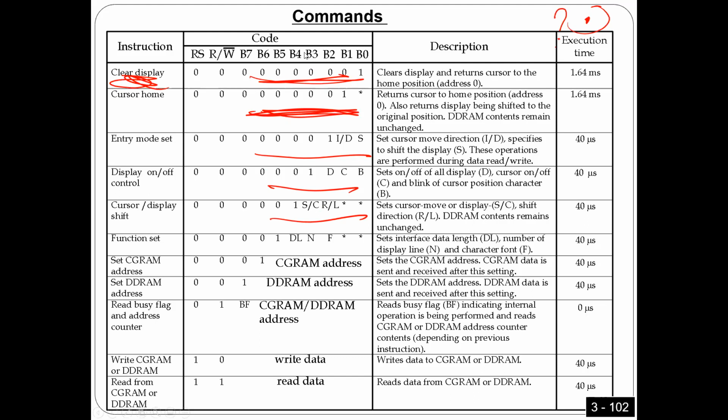They made it so that when you send this number, the hardware will do the display or whatever. So almost everything is the same, but maybe these numbers will change. That's why if you program a different LCD, you have to see what numbers they are using. The good thing is that for ASCII, for data, it's going to be the same, because this is something universal, global.